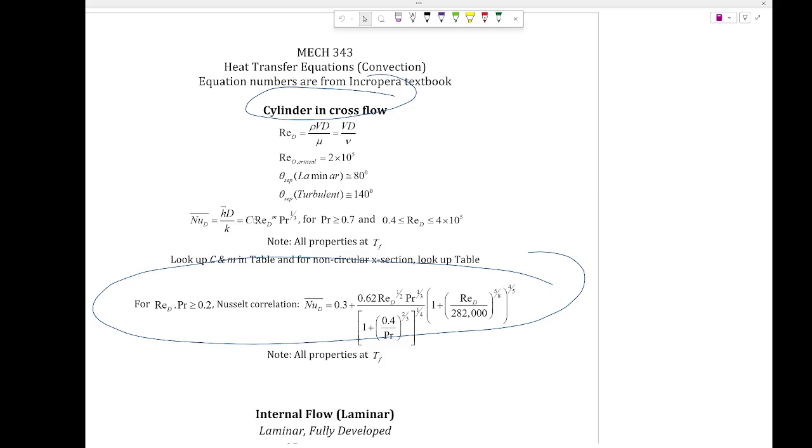Now, other than that, everything is pretty much straightforward. Why am I saying that? You're going to find the Nusselt number. You know what the Nusselt number is? It is hD over k, in this case D. In external flow over a plate, we have hL over k, right? Here it is D, so the diameter is known for my hand, assuming it's a cylinder. The k is known. It is the k of the air that is flowing there, remember that. The conductivity is not for my hand, it's for the air. So you can find the air's k from the appendix.